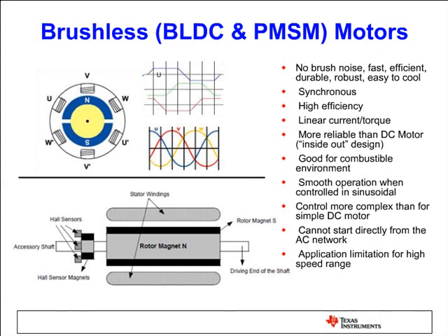But on the other hand, we hear lots of negative feedback about the BLDC operation, which I'm going to talk about in one of the next slides. So for high performance applications, people prefer PMSM type motors with sinusoidal back EMF.